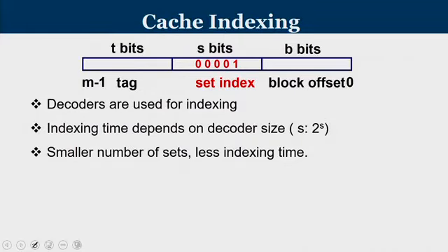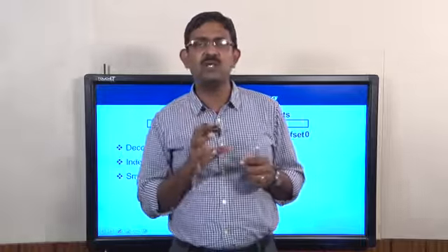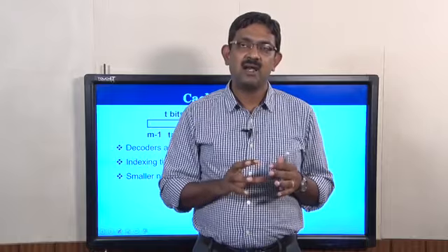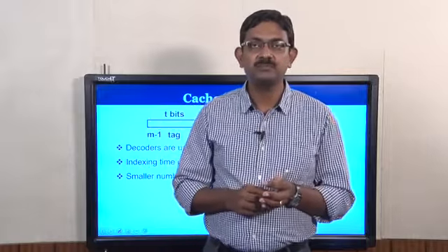Okay, to summarize what we have learned: we have learned about direct mapped cache, set associative cache and fully associative cache and their functioning. The set index is used to localize your search inside the cache memory, so in a cache we do not search the entire location. A few bits in the address are extracted, and these bits tell you where to look in the cache. Once you go to the location, the tag tells you whether the data stored there is the same as what you are looking for. And once you get the hit, you use the offset to extract the data.